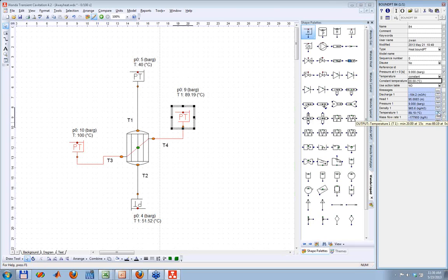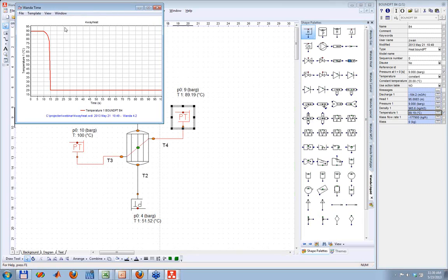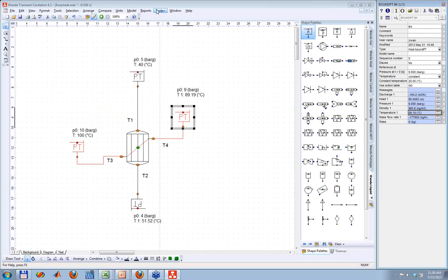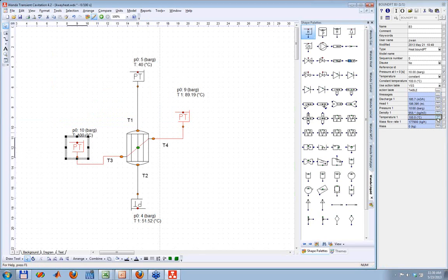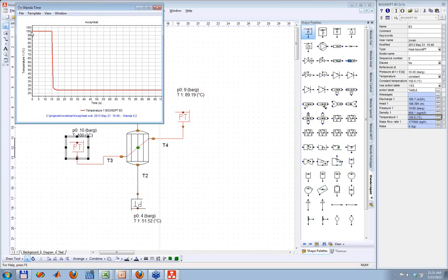If you look at the temperature here, the time series, you see it starts to drop because the flow rate will decrease. At a certain moment the flow reverses, and then it starts to supply water at 20 degrees, and then it's constant. We then look at the other side, the temperature. You see it's first supplying at 100 degrees Celsius, and at that moment the flow reverses and it's not supplying but receiving, and then you can see it receives water which is about 25 degrees Celsius, and it decreases a little because the flow is still increasing, and then it stays constant.